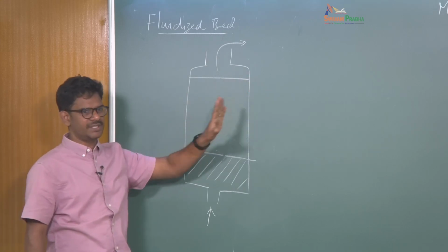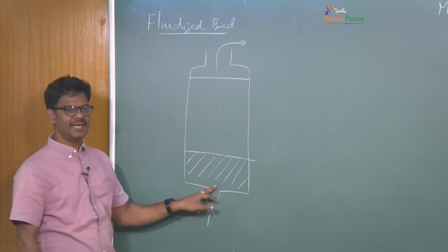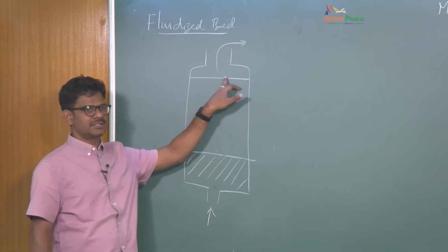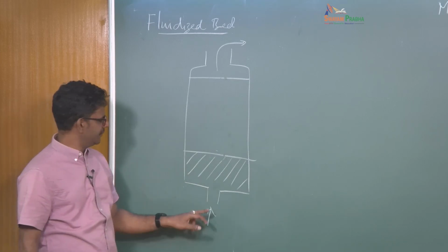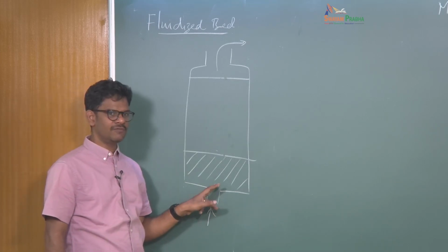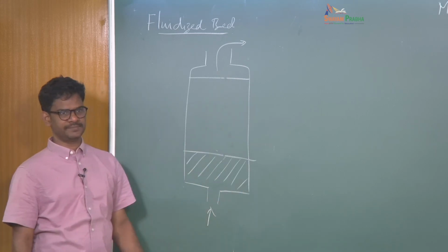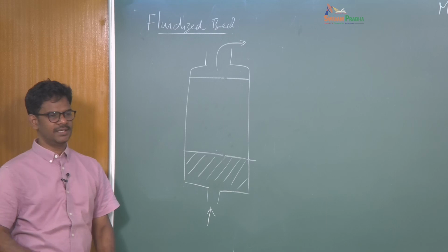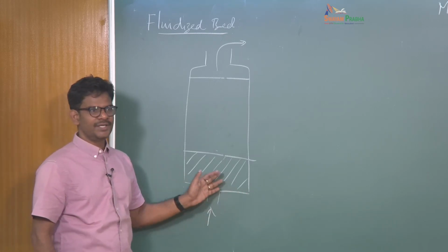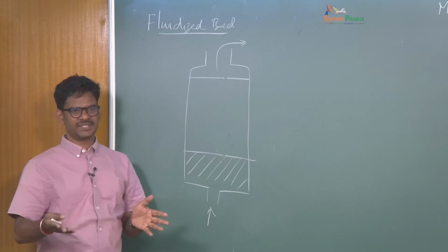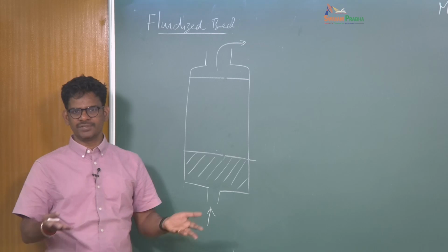When the particle comes here, you either take it out or maybe you can reintroduce it later, and so on. There are many combinations, but what I am going to do is a very simple boundary condition. Particle enters here and then gets absorbed here. That's a very simplistic thing. Then you are asking the question, if I start a particle here, how long does it take to go from here to here? That is essentially the residence time for this particle. A large number of particles can be introduced here, then you get a distribution of residence time, and by that we can get the mean residence time for this kind of reactor.